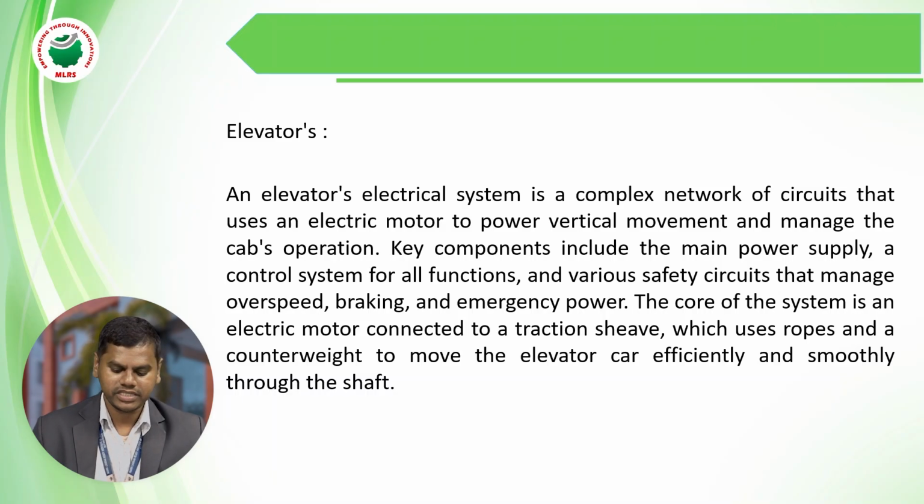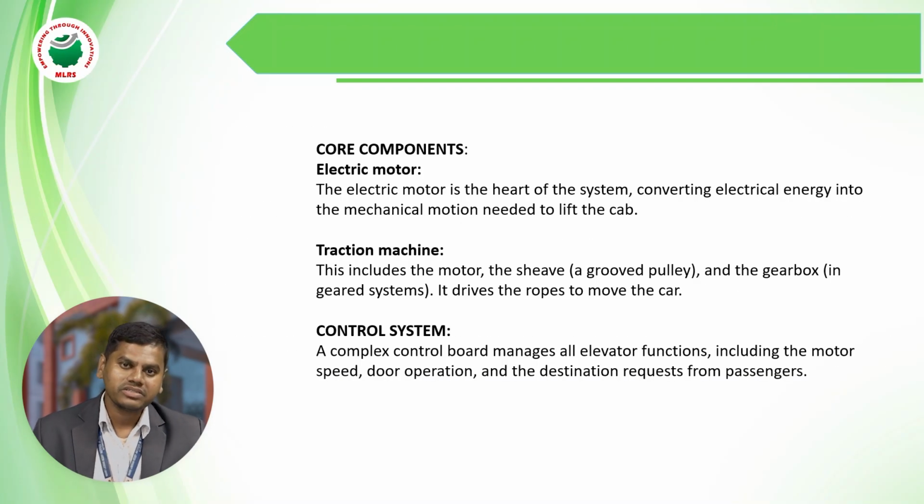The key components include the main power supply, a control system for all functions, and various safety circuits that manage overspeed, braking, and emergency power. The core of the system is an electric motor connected to a traction sheave, which uses ropes and a counterweight to move the elevator car efficiently and smoothly through the shaft. So what are the core components of the elevator?